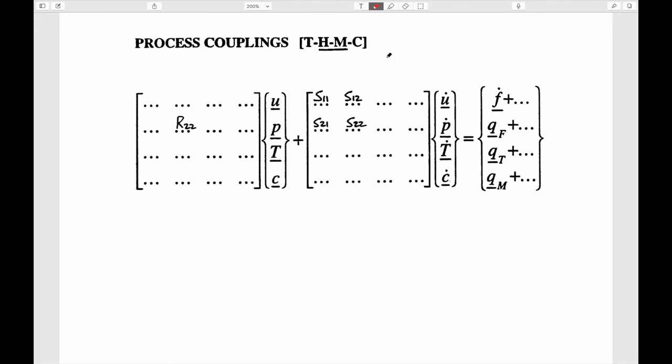So the systems that we would deal with would be something like, for solid mechanics, F equals Ku. And for the flow part, Q is equal to K, we'll use pressure rather than head, plus a time derivative of pressure. And these are all submatrices.